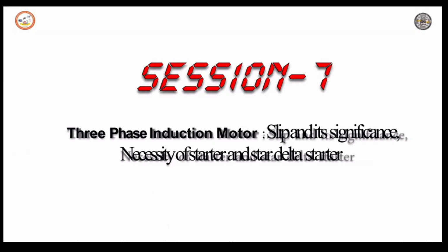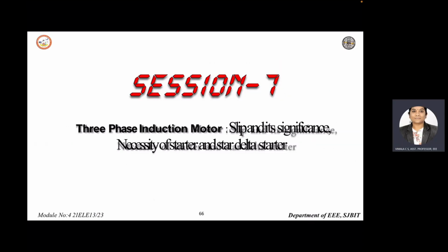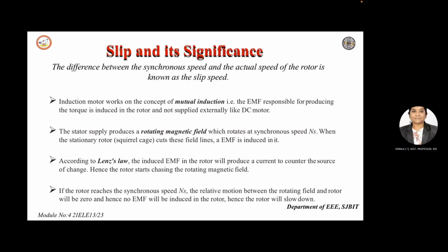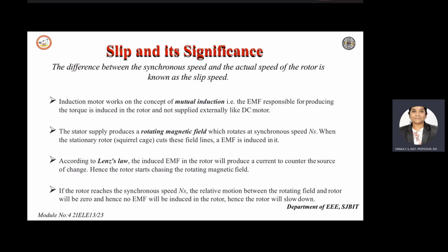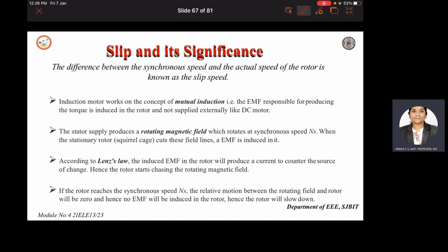Induction motor slip and its significance, and we are going to discuss the necessity of the starter which is connected in star delta connection for the induction motor. The difference between the synchronous speed and the actual speed of the rotor is known as the slip speed. Normally we write the slip speed as Ns minus N.